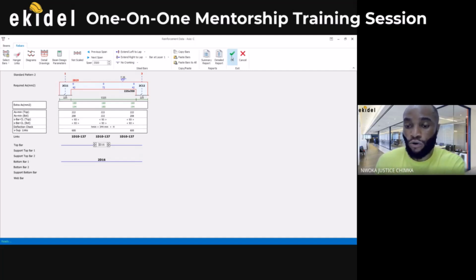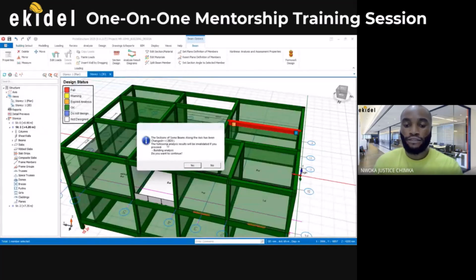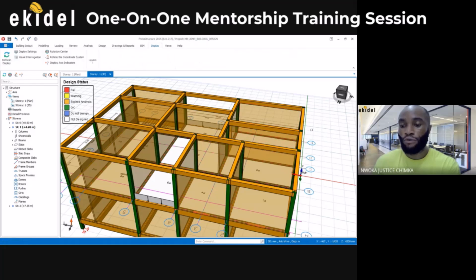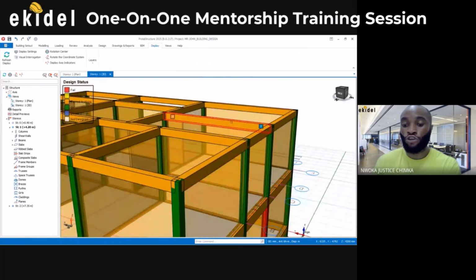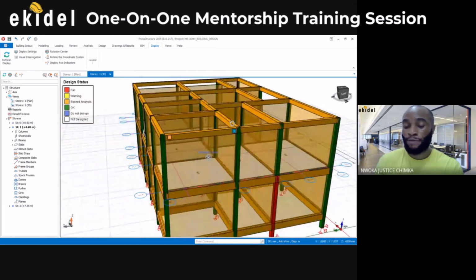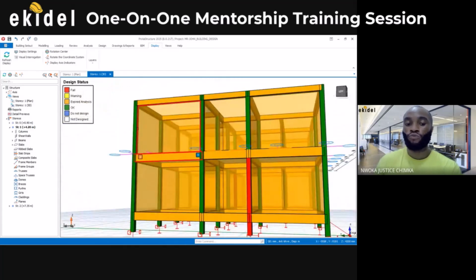If I come down and say okay, you can see that we have made changes to our section, so the building analysis will be cancelled. If I say yes, it will show the expired analysis, and everything here will be showing orange color. I'll say yes because I want to take the new changes. The beam will now show red again, showing that all the testing we did on the beam has expired, but the columns are still okay because we didn't touch the column.